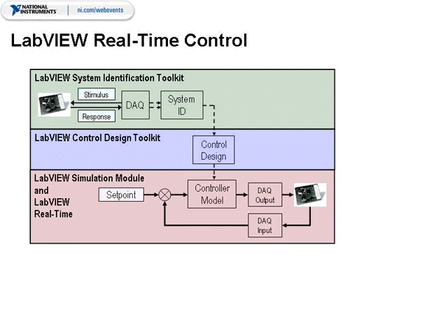In addition, this same LabVIEW simulation module can be used together with LabVIEW real-time for implementation. So the diagram that previously had the plant model has now been replaced with data acquisition functions for output and input, such that the controller can be interfaced to the actual physical plant of the system that you would like to control.